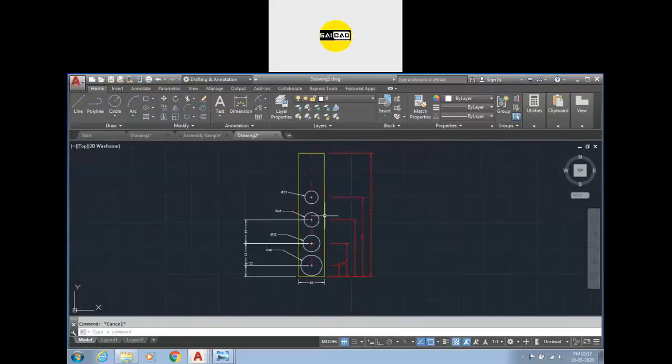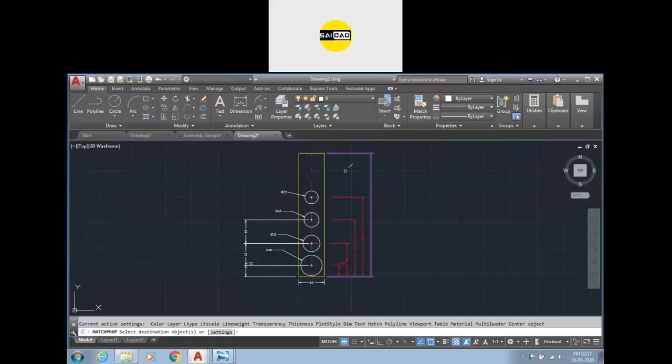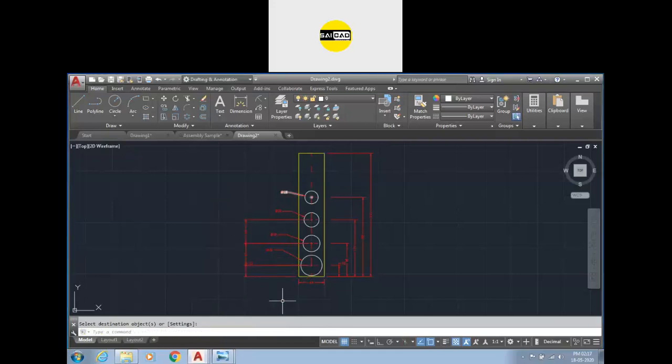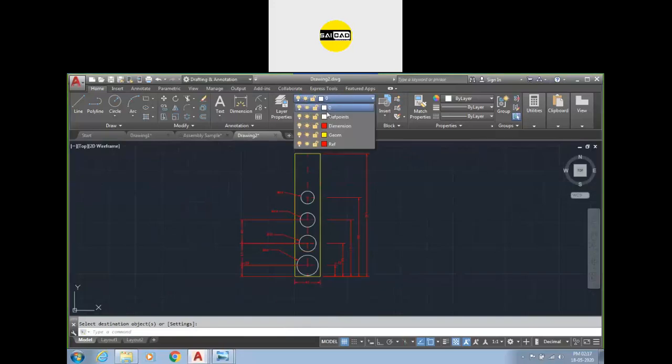If you want to match the properties directly, you have this option here, match property. Select the source. I want this object's properties to be matched with all of these. So select all of these like that, or just click on that. So all the properties can be applied like that. Now what is the advantage? I can just go here and turn off the dimensions.